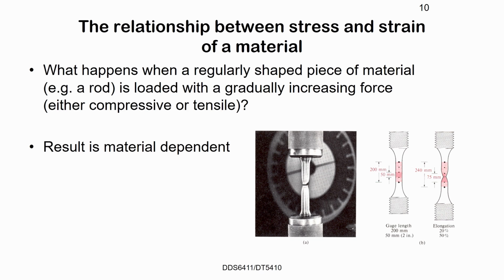Could you explain what you mentioned about ultimate strength and maximum strength? That's the maximum strength, because that's the highest point along the curve. And that's the ultimate strength. That's when things break, the breaking point right here. But it's lower on this curve because we are using the original cross-section to calculate that.